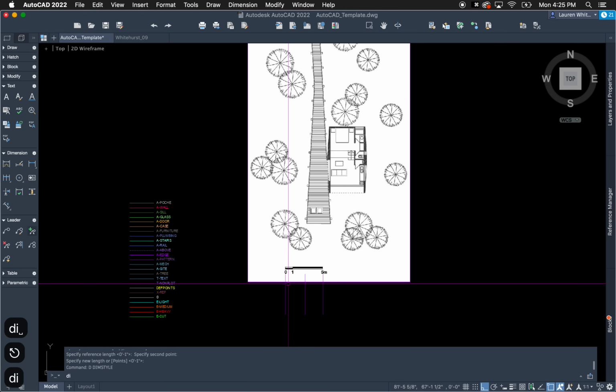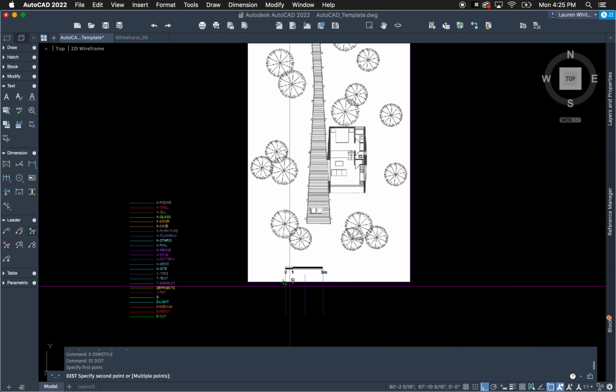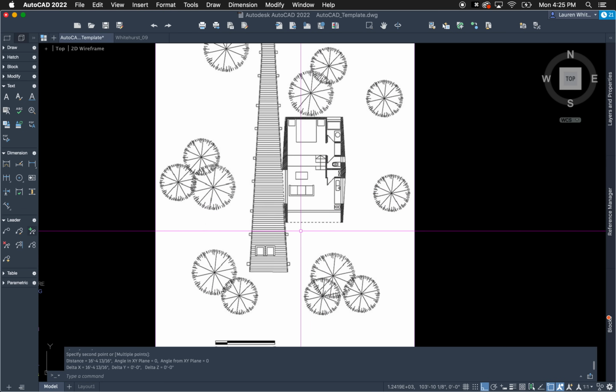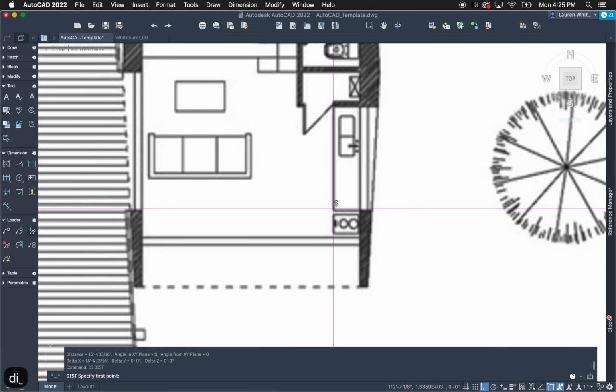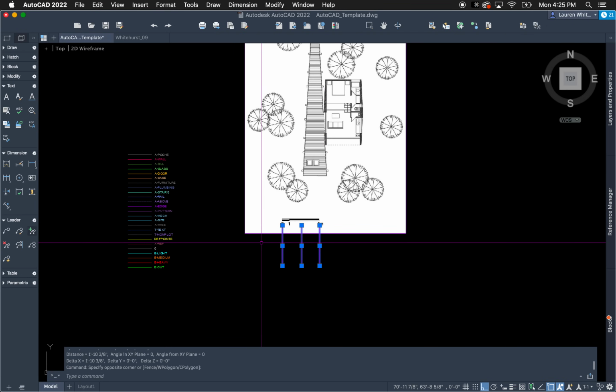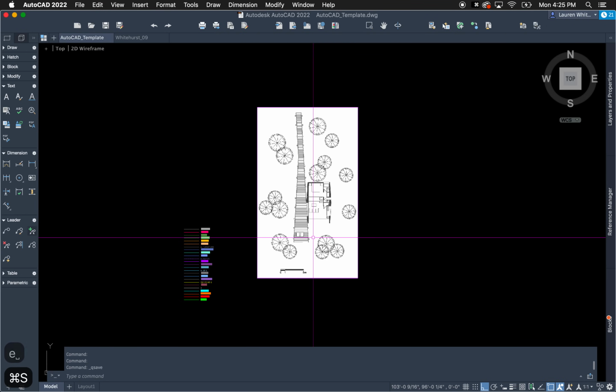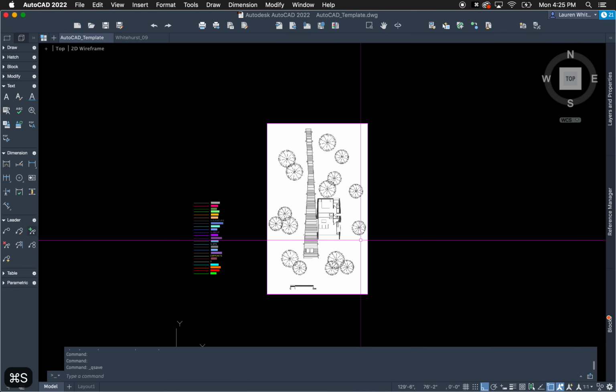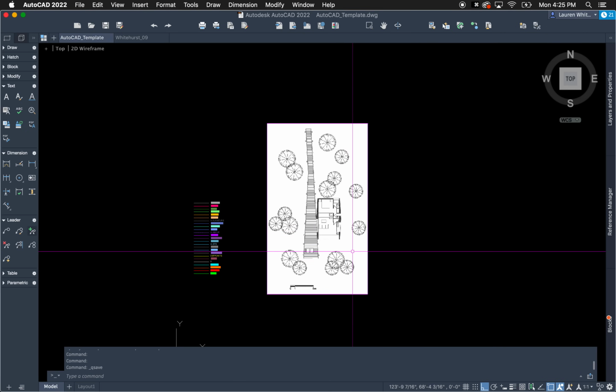So now I'm just going to test this. If I type DI, it's just distance. If I click and click again, that's about 16.4 feet. So that tells me that the drawing is, at least according to this scale, correct. Another thing to check is roughly, if I know a sink is normally around 2 feet or so, sometimes a little shallower, that's close enough to 2 feet. So I'm comfortable with this drawing being to scale enough. So scale the image of your building first, and then you can use that to trace and then draft with.